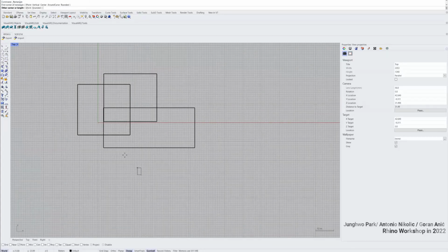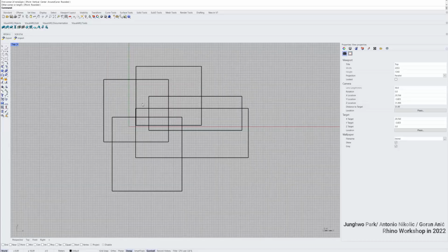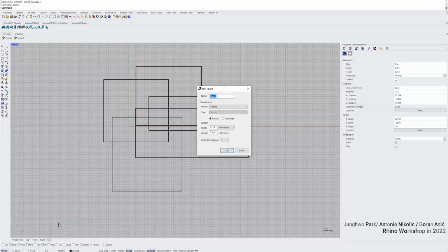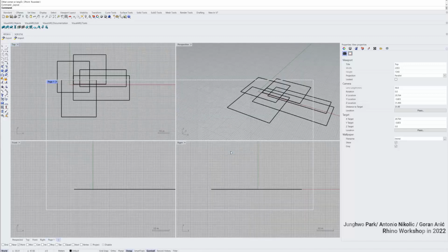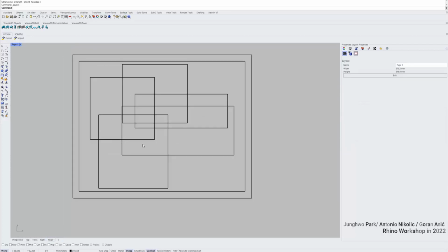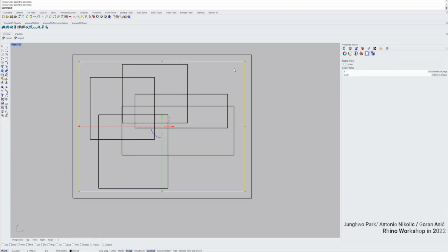And also you can put these in the layout. Right now we are just printing in the viewport like AutoCAD. When you have model view, you can print it there, right? In AutoCAD. And in Rhino, you can also add one more new layout, for instance. And you can name it plan or whatever. And you can already set it before. I'll set Rhino PDF, and you can define the size of the space. And this is already your layout, yeah.